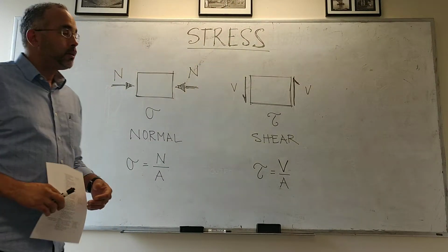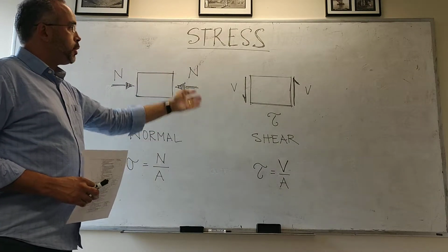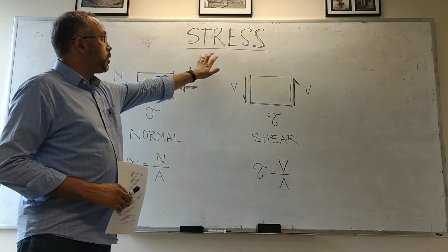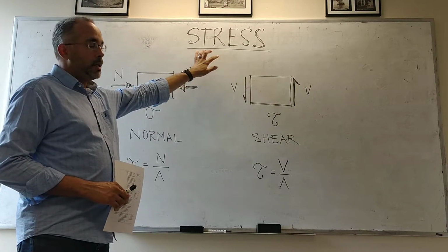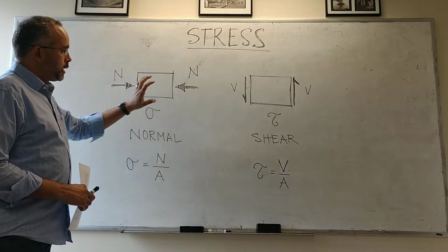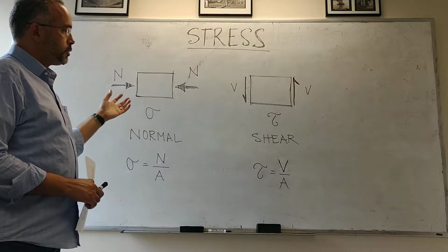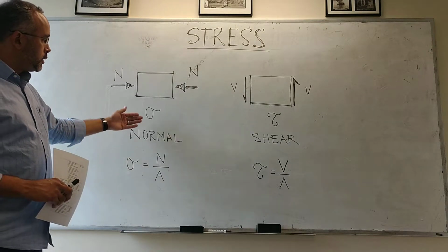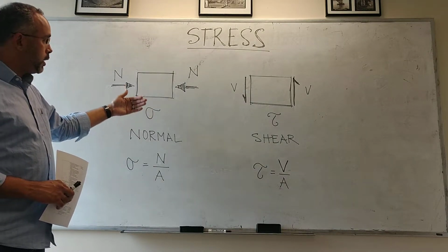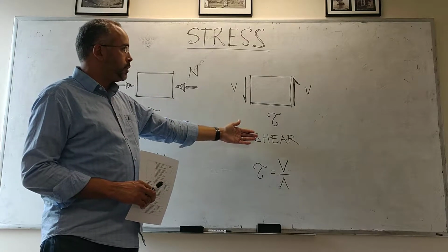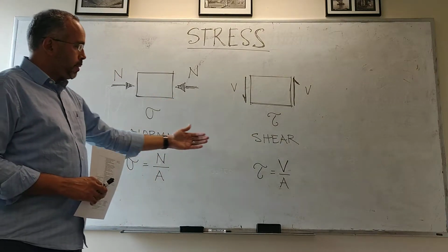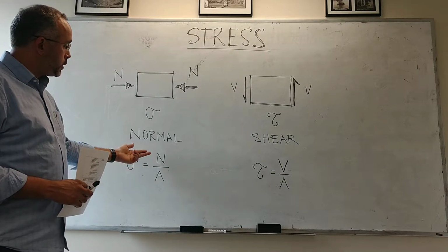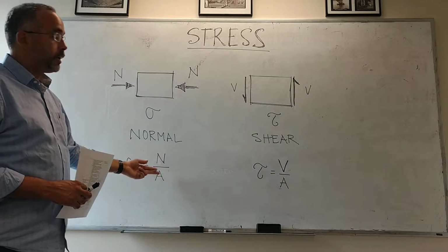In this session, we're going to discuss probably the most important concept in mechanics of materials, which is the concept of stress. Basically, we are interested in two types of stress that are commonly found in materials and structures, normal stress and shear stress. Both of them are basically a manifestation of the same idea, which is a force divided by an area.